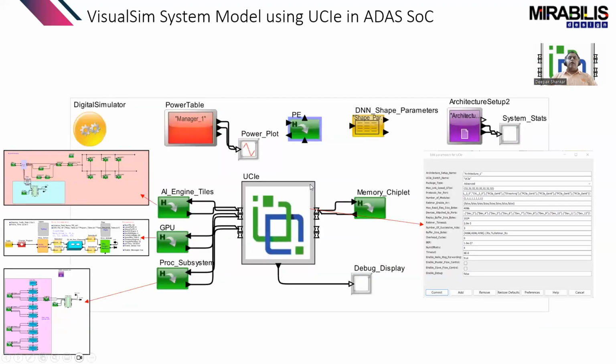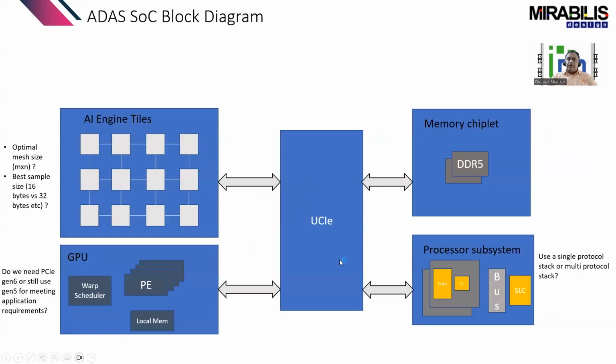Then, of course, there's overhead in the backbone of the UCIe subsystem. So there are a lot of additional delays. You can very easily add about 32 to 36 extra nanoseconds for data to go across. So really, it's not too effective for this to be going here and picking up data and coming back, unless it's background data or I'm just doing an IO read and doing a DMA transfer.